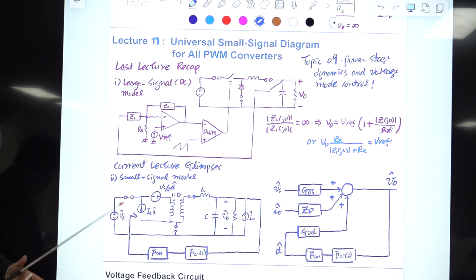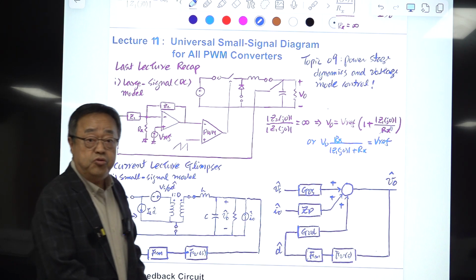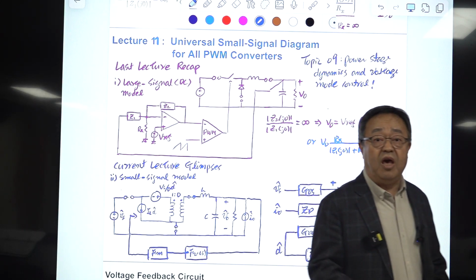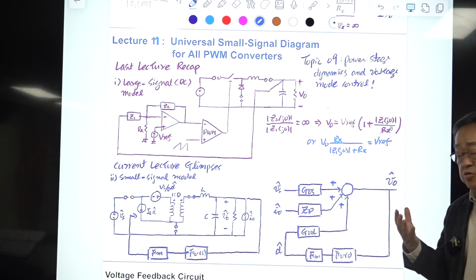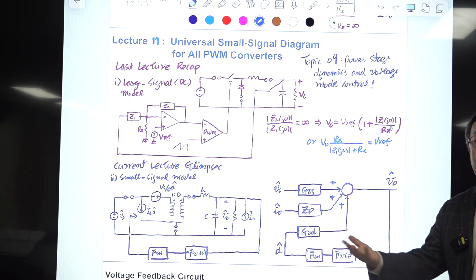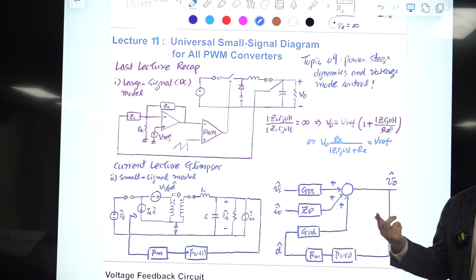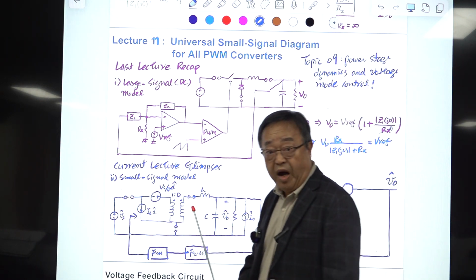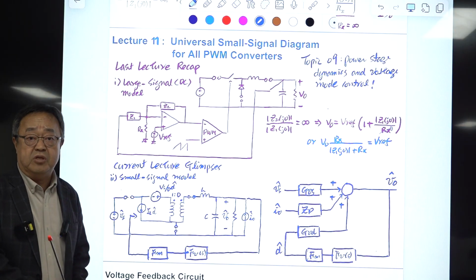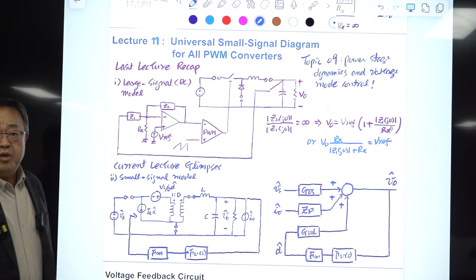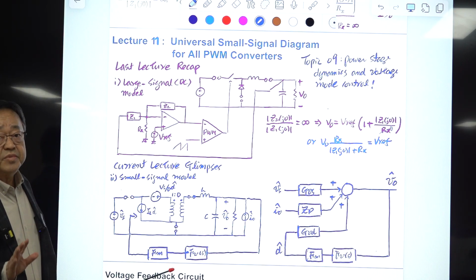And this is the voltage feedback compensation. We need a negative sign here always, okay? I forgot that. And this is the modulator gain. You may use the linear gain, a constant value, 1 over the height of the ramp. That is fine if you understand the high frequency characteristic of the describing function of the modulator gain. And the loop gain crossover frequency is way below the switching frequency, so that will be fine.